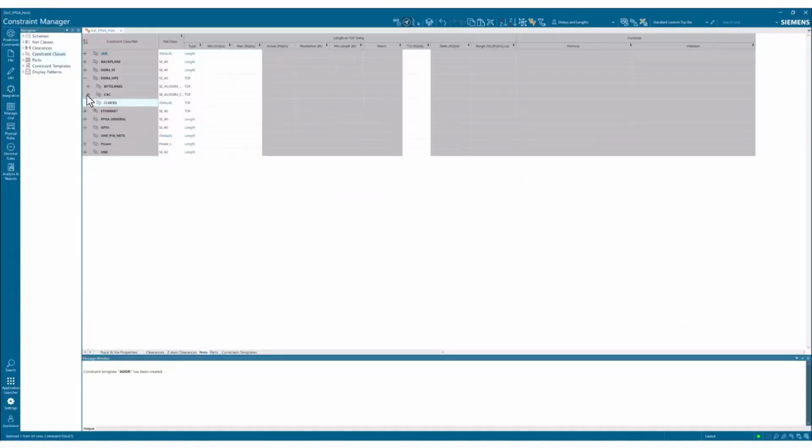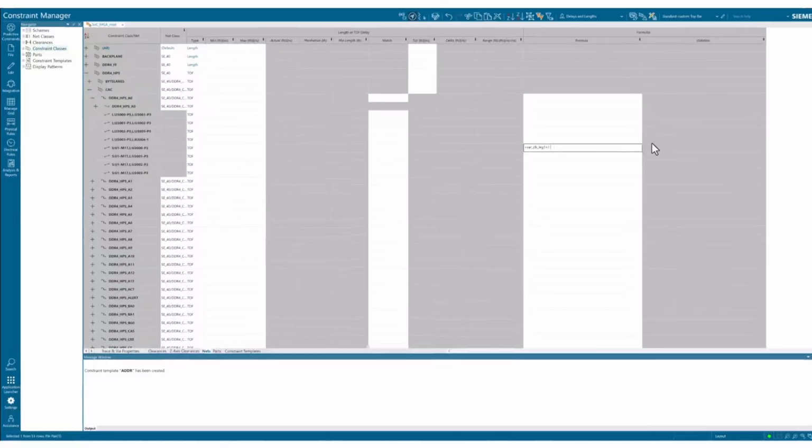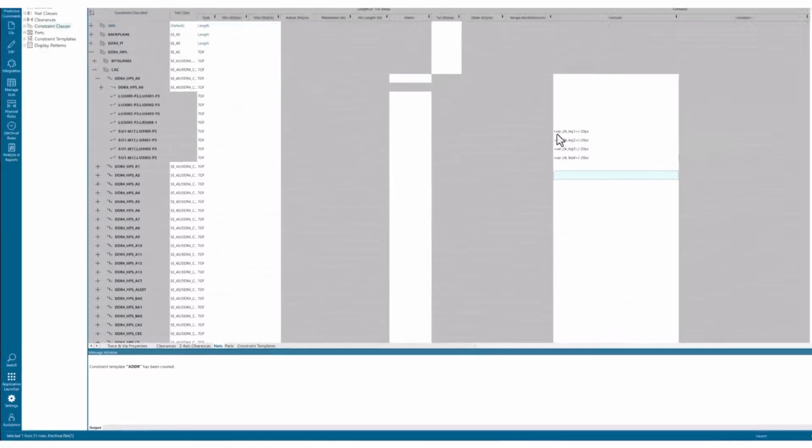Okay, so now we'll go handle these same rules on the address and strobe sides. For address signals, I'm just going to pull out one of those nets. We can do address 0. And I have the same pin pair setup for that already. So I'm going to put the same formulas. The smart thing to do probably would have been to copy this over before I set up these strobe formulas, but since I didn't do that, I'm just rewriting them. You can do it either way.